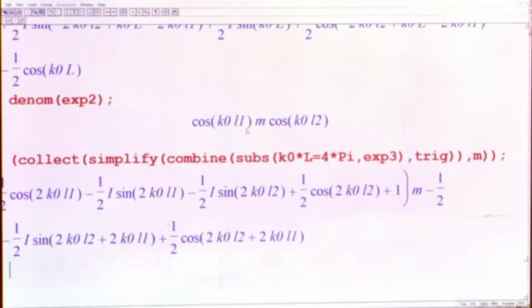So, that will happen when L1 is equal to L by 2, L2 is equal to L by 4, and for the frequencies k naught L equal to pi or 2 pi or 3 pi. However, at k naught L equal to pi, but L1 not equal to L by 2, you would see that theoretically you would be getting a peak. So, although it is a bit tedious to explain it here, we have done decently in explaining the basic behavior of the extensions, what extensions can do in terms of uplifting the trough.